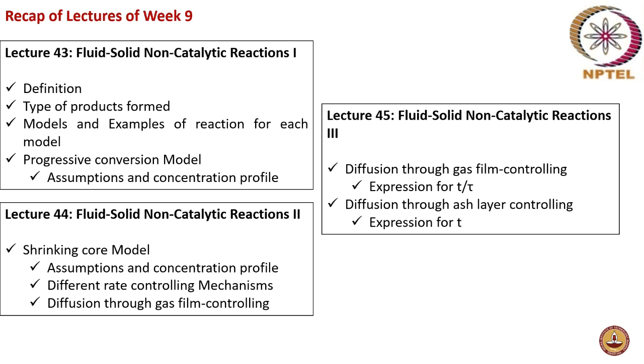So in a non catalytic reaction, the solid is one of the reactants, right? The solid and a fluid, both of them will be reactants, and the product might be either only fluid or only solid or a combination of fluid and solid. Correct? That is what happens in a fluid solid non catalytic reaction.